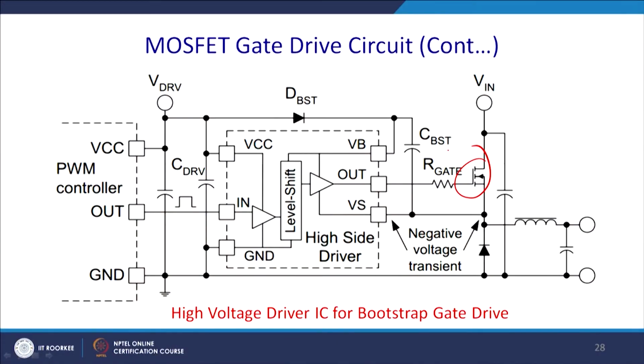But in any kind of application, when you trigger it and the voltage goes to plus VCC, the gate voltage is lower than the source voltage, so the voltage polarity reverses in VGS, and it will find difficulty turning that MOSFET on. For this reason we require some modification to the circuit, and we provide a capacitor called the bootstrapping capacitor, and this method is called bootstrapping.